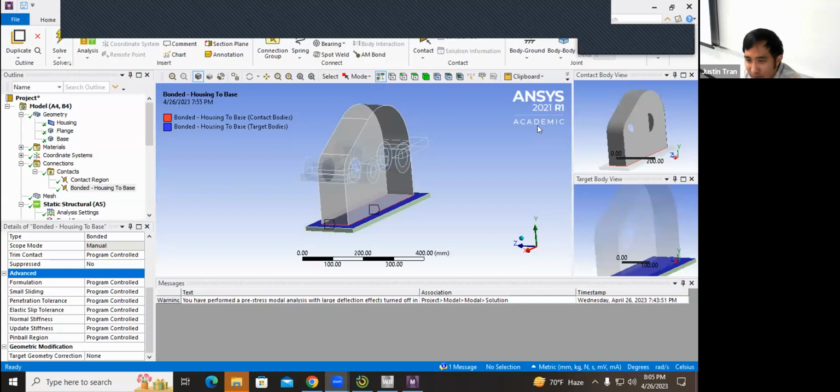One of my main problems with my midterm project was that I practically spent most of the time just trying to refine the mesh, and trying to find a mesh that actually can be computed. A difference of a millimeter almost doubled the number of elements.